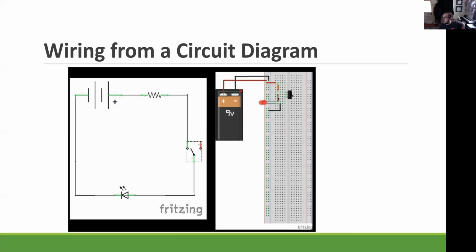So we get that wire from the LED to the positive, goes through, which then connects to the negative via the black wire, which, as you'll see here, positive, resistor, switch, nothing's connected to that third pin. So it's either connected or not to the LED, nothing happens, which then works its way straight back to ground. So you can kind of compare A to B. These are the exact same thing.